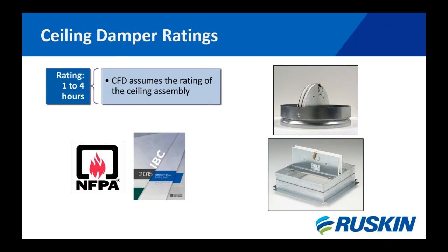You can see there by the photos, we have radiation dampers available in a true round, also in square and rectangular sizes. Size is going to be important because every UL ceiling design is going to have limitations on the allowed opening area per a given space. So typically it's going to read like 324 square inches per every 100 square feet of ceiling space. So that's the one important thing that all designs are going to note, is the allowed opening space.